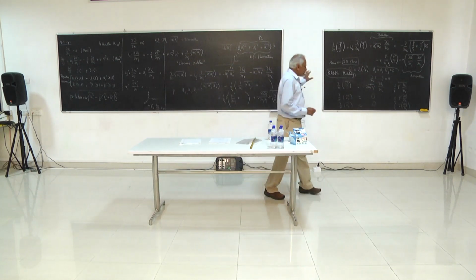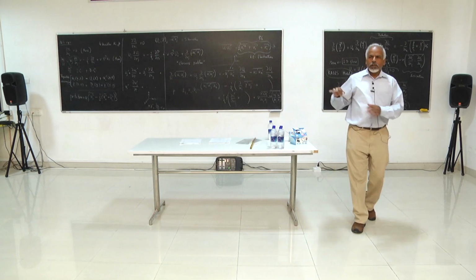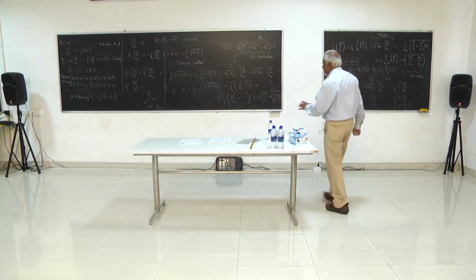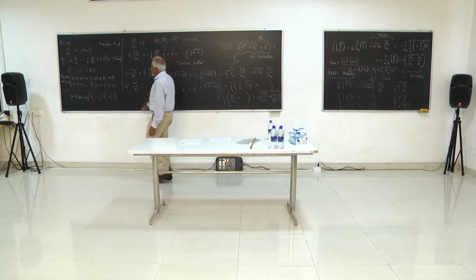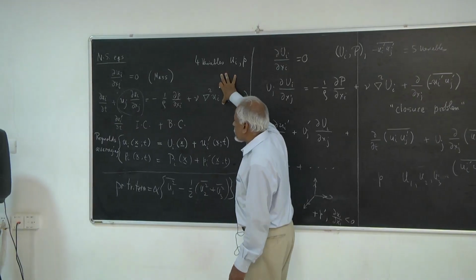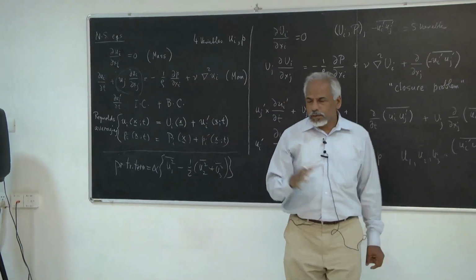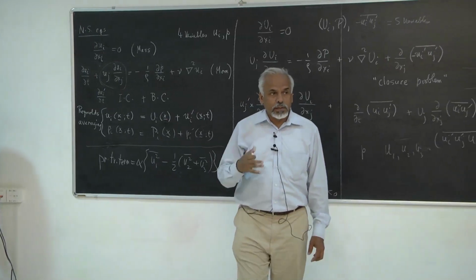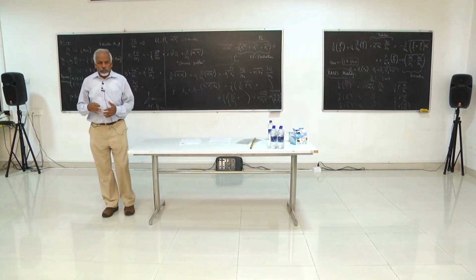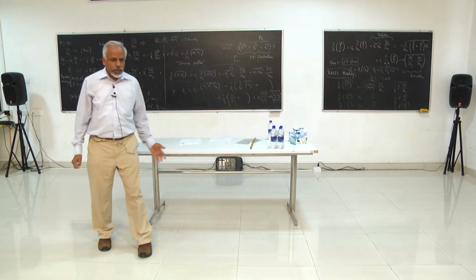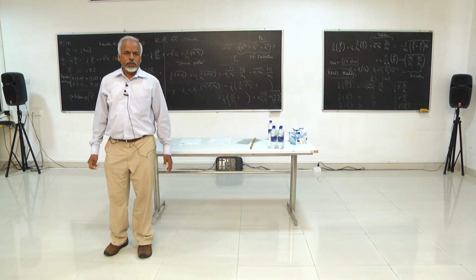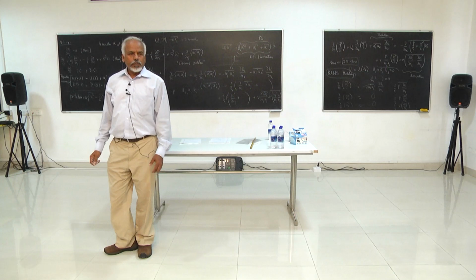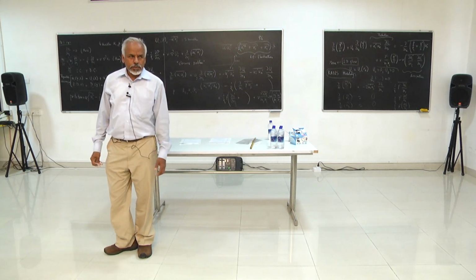Okay, so is this roughly clear, the situation? I mean, you may not have followed all the details, but the general philosophy must be very obvious. I'll repeat it for you again. So you have these equations that are known to you, given to us by God himself or herself. And then usually, by the way, these Navier-Stokes equations are derived by a process applied to Boltzmann equations. So people think that this is an approximate form of the Boltzmann equation.